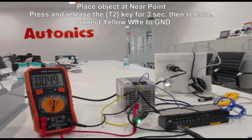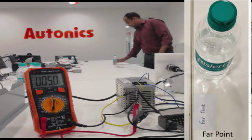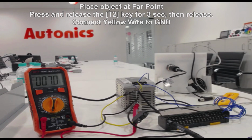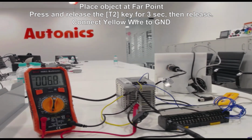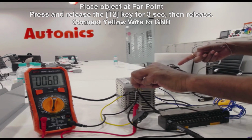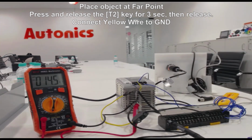Now let me keep the bottle at far point. Now I need to again press T1 key for 3 seconds. Sorry, T2 key for 3 seconds. 1, 2, 3. So the far point has been taught.